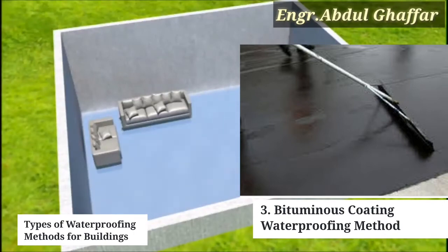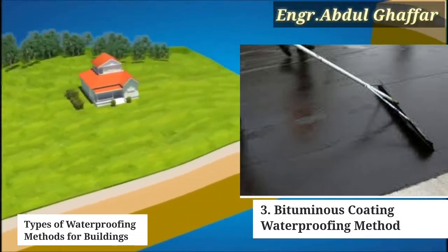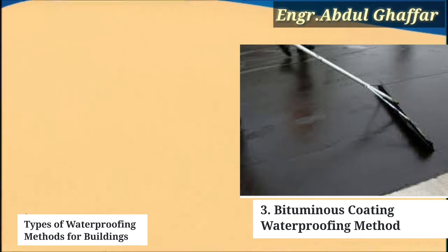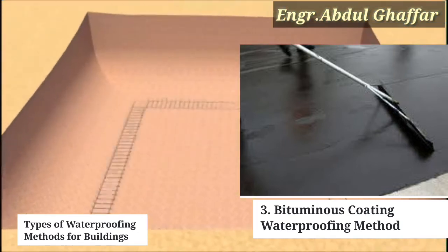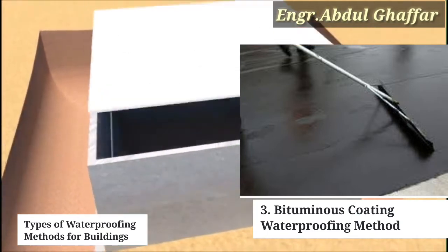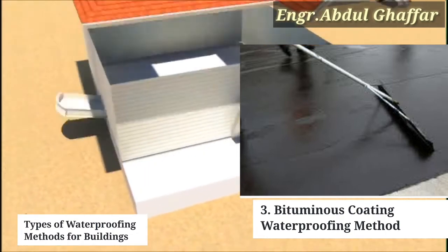It becomes very brittle and fragile with long exposure to sunlight unless it is modified with more flexible material such as polyurethane or acrylic-based polymers. The flexibility of the finished products always depends on the solid content of the polymer added to the bitumen.